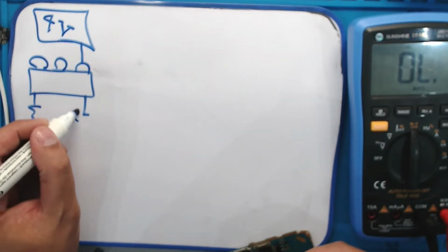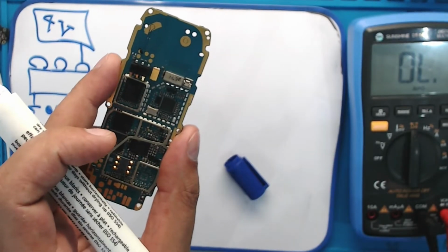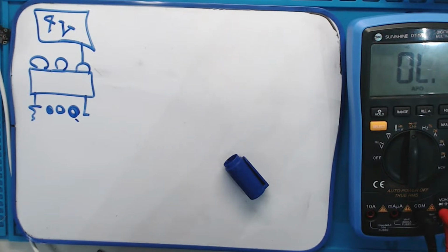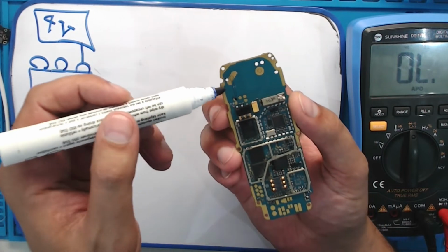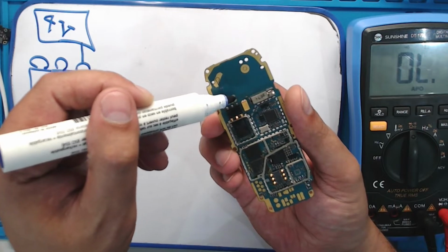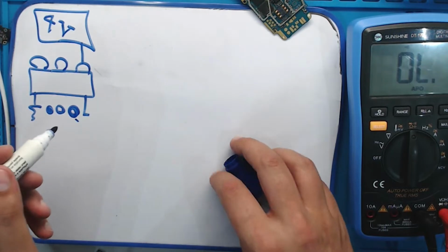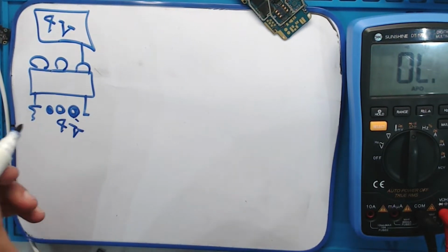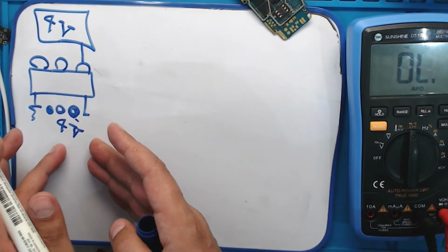And on the motherboard there are a few test points like this. Just give me 1 second. Yes, this is correct. You see around the battery connector there are these circles. This is the test point. I'll show you how to test the voltage. You can check here to find whether the 4 volts is present or not. This 4 volts voltage is coming here, and you know that voltage comes inside the motherboard.